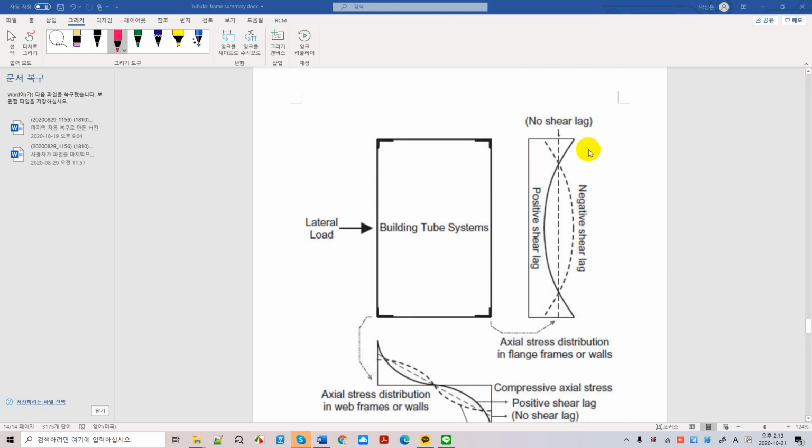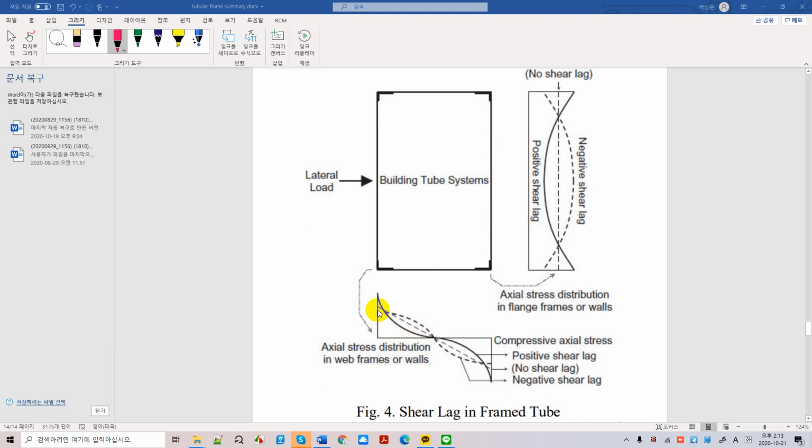And you have the same distribution of vertical load of columns on the compression face if you have perfect shear stiffness for girders, so that the shear deformations can be prevented. Then you have your straight line distributions, no shear lag. And here, if you have no shear lag, then you have a straight line in this line, right?